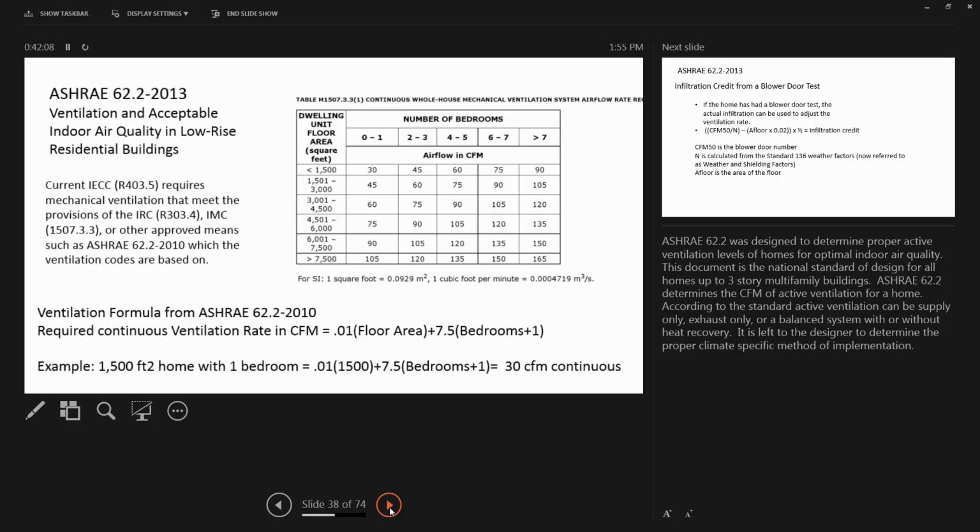One of the biggest challenges, and we don't see it so much in our climate zone, but in any other climate zone that's got a significant amount of moisture, is mold growth inside the walls. It's becoming probably one of the biggest and most heavily litigated building envelope failures in the country. And it comes from lack of ventilation, lack of proper installation of air barriers and vapor barriers.